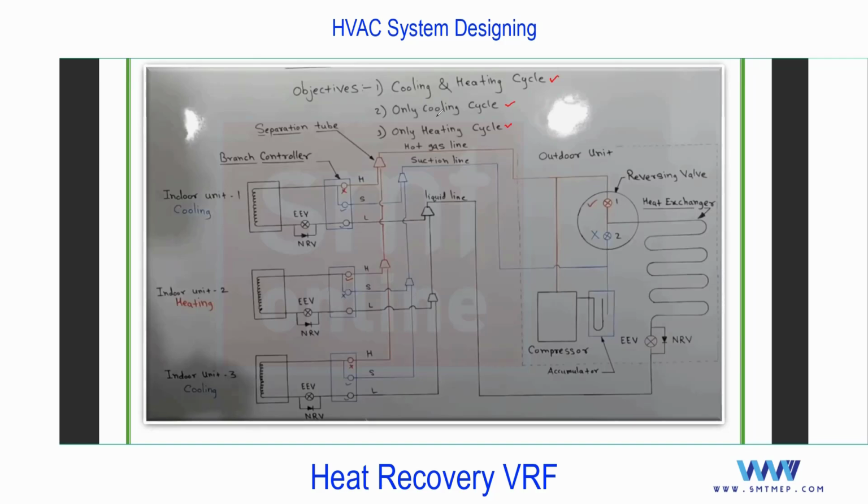If you talk about only cooling, you see I'm using only cooling mode. You see what we discussed in the heat pump, the same plus some more additional options. And the first point here is that this is a 3-pipe system. Only cooling or heat pump is a 2-pipe system, but this heat recovery is a 3-pipe system. Important from an interview point of view.